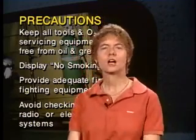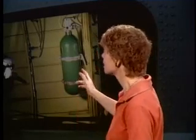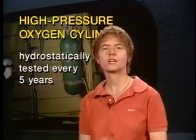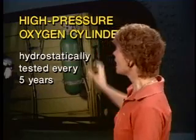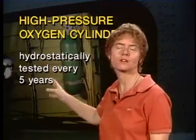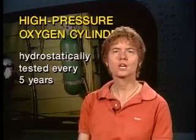Now, you may need to determine the serviceability of oxygen cylinders. They have to be the correct type, and they have to have been hydrostatically pressure tested with water within the proper time interval. What hydrostatically tested means is that they put water pressure inside it and pump it up to see if it cracks or breaks, taking it up to the pressure limits that they're supposed to for proper testing. A high-pressure oxygen cylinder has to be hydrostatically tested every 5 years. A standard weight high-pressure cylinder needs to be tested every 5 years.